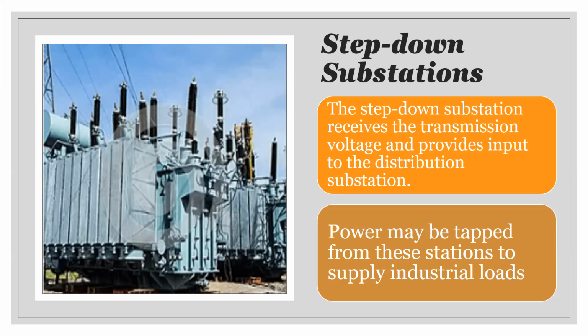a step-down substation. So in the UK, for example, the distribution substations are taking in 132 kilovolts, coming down from 400 kilovolts in terms of the major transmission lines. So at 132, you would take that down and supply it to a lower substation, which would be a distribution substation. And then the distribution substation would pass the voltage out on the streets, okay? Additionally, coming from these step-down substations, that 132, as the second point is highlighting here, may go directly to industrial facilities.